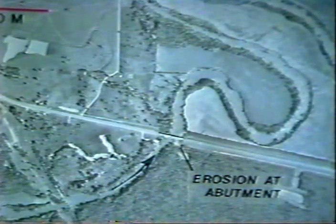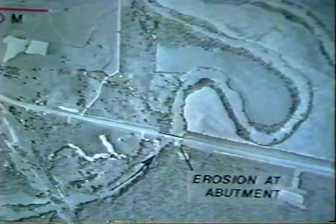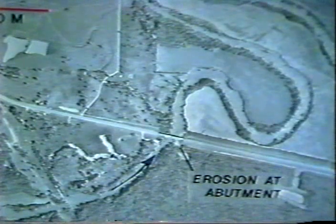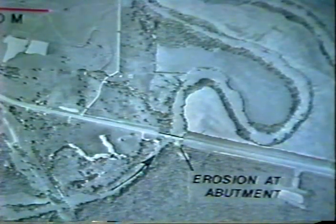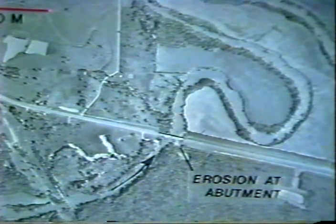This bridge on the Sulphur River in Arkansas was built in 1931, and no hydraulic problems were reported until after closure of an upstream reservoir in 1953. Sustained flow releases, above normal but below bank full stage, evidently increased the rate of lateral erosion. The right bridge abutment was most affected because it is at the outside of a bend. Lateral erosion at the bridge and along the channel downstream was increased by removal of natural vegetation and by a natural tendency of the banks to fail by slumping.